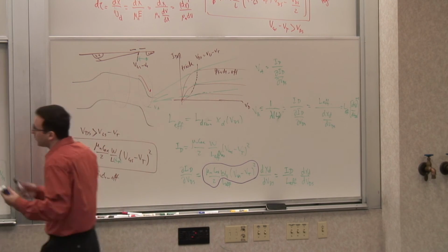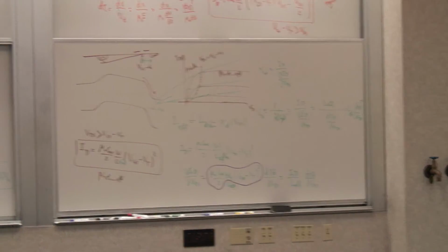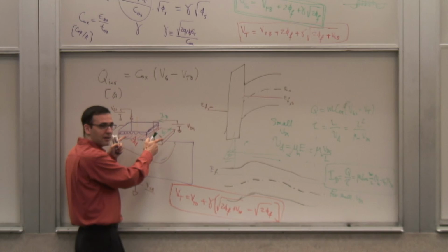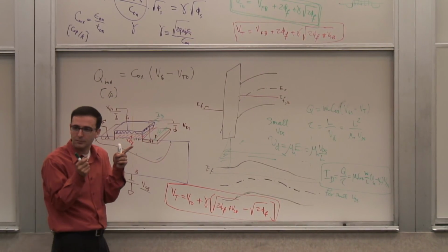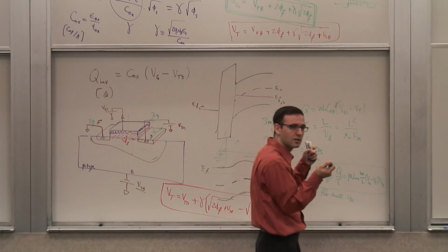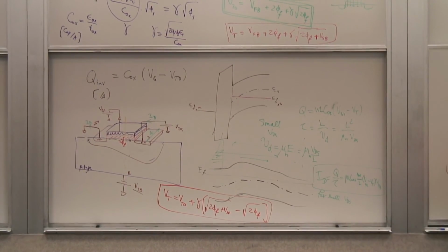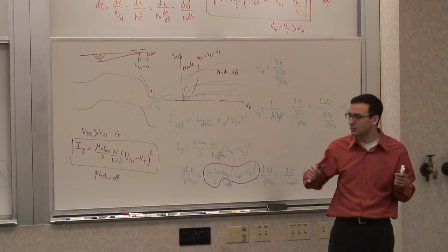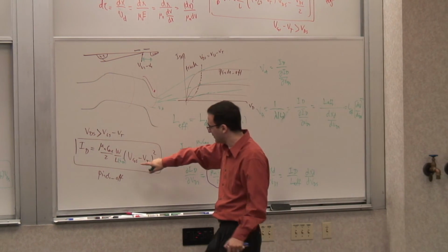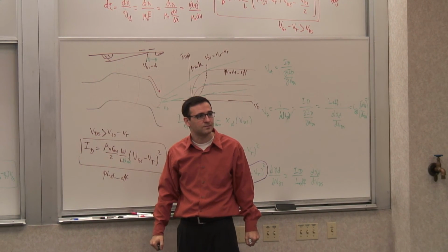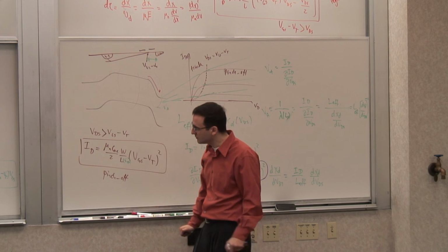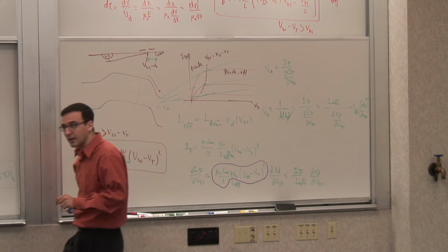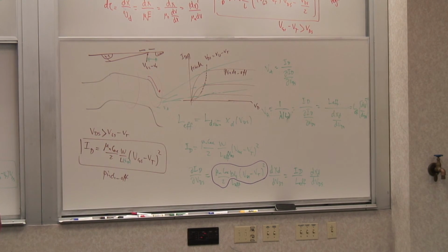So if I want to make one of my transistors larger, I can give that one transistor a larger channel length. So I have two degrees of freedom to play with in a MOSFET, which gives me more versatility. And if there's one transistor in which I need a large output resistance or large VA, I can make L large in that transistor. Okay, so that's for that. Any questions on this?